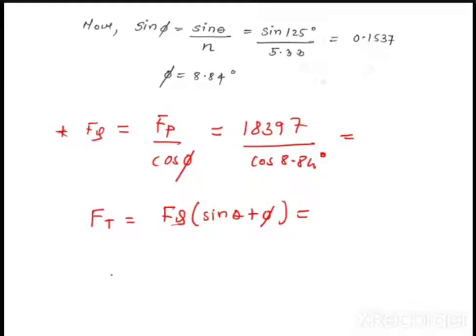Similarly, once you have calculated Fp, what is the final aim? You have to calculate T, the turning moment or torque acting on the crankshaft. So the torque on the crankshaft is Ft into R. If anybody has a calculator, you can tell the values. Finally, they have told you to calculate the effective turning moment on the crankshaft, that is T. In this way I will get my final answer.